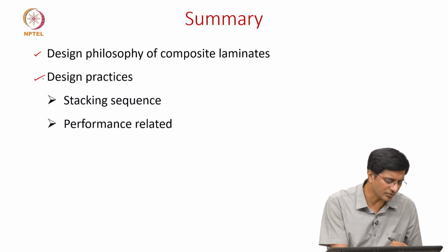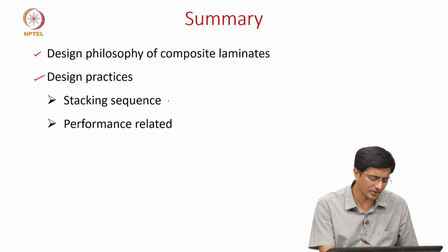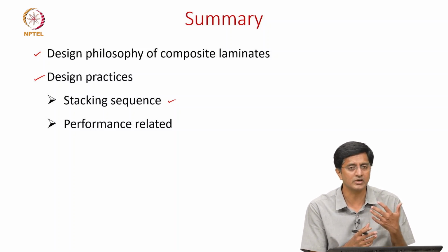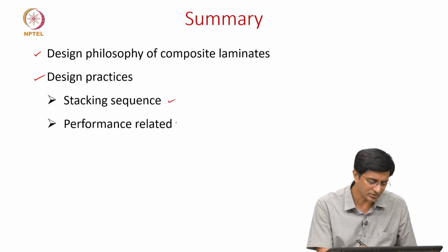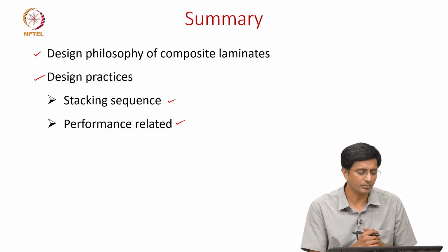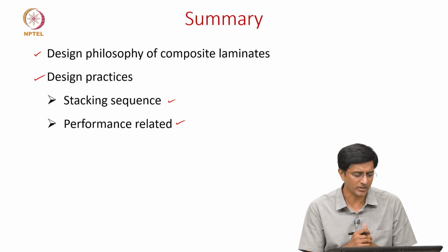Later, we also discussed a few design principles or design practices. First, we looked at various stacking sequences, saying there are some stacking sequences which can avoid some of the couplings we commonly discuss. And later, we also discussed a few suggestions to improve the performance of the composite, like the bending stiffness, or how we decide the sequence if there are in-plane shear loads, or if we expect some low velocity impact damages. So this should summarize what we have discussed.